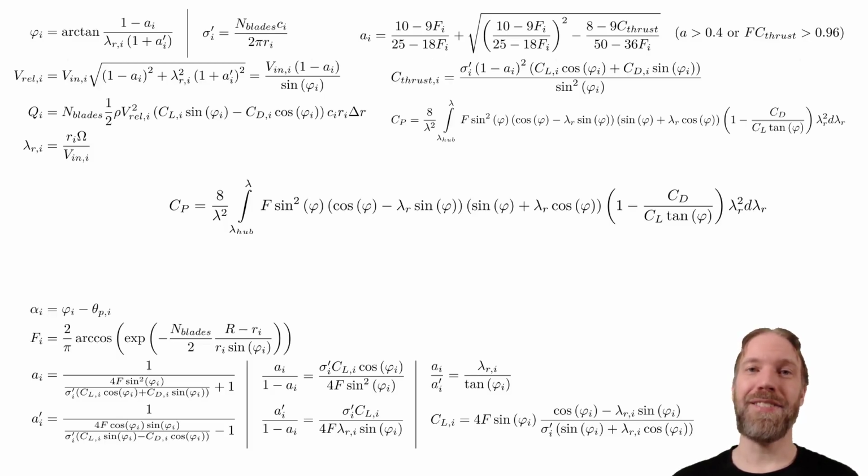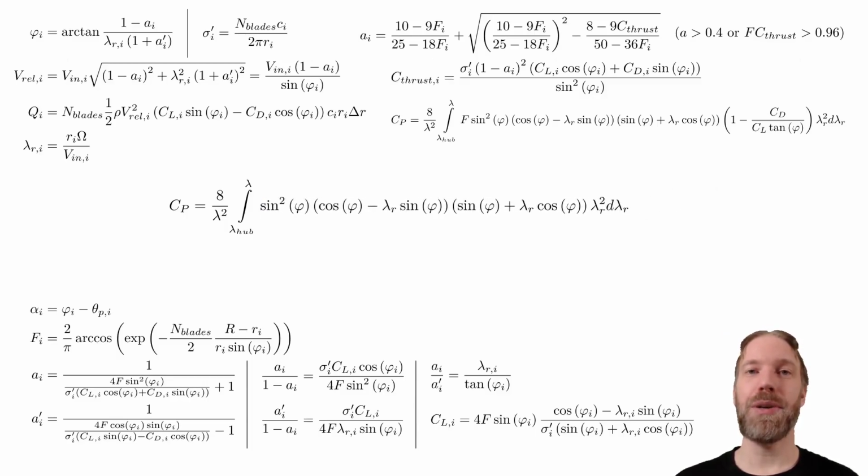As the correction factor F is relatively complicated, we will likely need to solve this equation numerically in its current form. If we introduce some simplifications though, we can derive expression for both the optimal angle of relative wind and the corresponding optimal chord. Here we will assume that the correction factor is 1 and that we can neglect drag. Neglecting drag will give too high power coefficient, but we assume that that effect on the optimal chord is much smaller, which makes it a reasonable approximation.